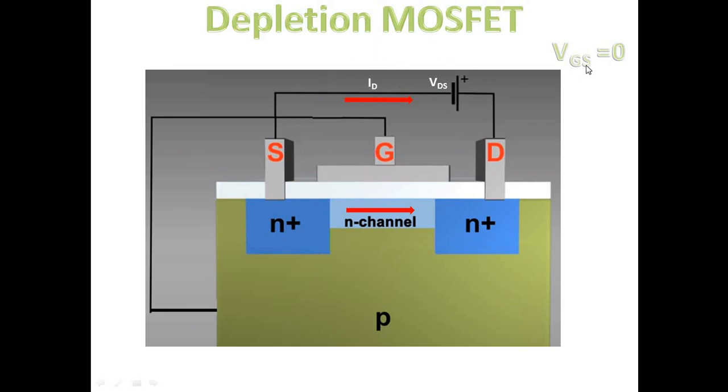Here you can see that I have again short-circuited the gate and the source terminal to make sure that VGS, the gate to source voltage, is 0. That is my control voltage. If you remember, throughout the field effect transistor, VGS is my control voltage, and that is still 0. So based on this, if I try to draw the basic idea of how the circuit works, then